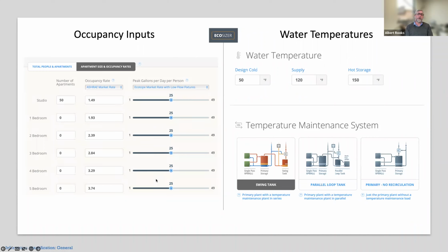What's our supply temperature? So what are we going to set the mixing valve? And as it leaves the mixing valve and hits the fixture units, what's that temperature going to be? Okay, we pick a number, 120, 125. You can run a scenario with 120. You can run the same scenario, don't change anything, change supply temperature to 125, and you can see how it'll vary, because the next screen, as we start getting information back, is super interesting.